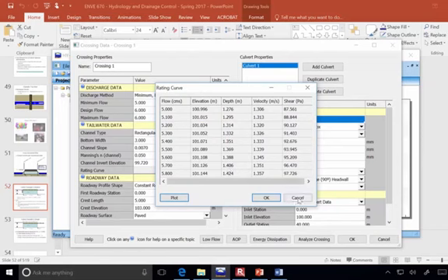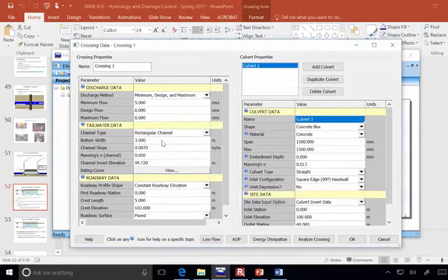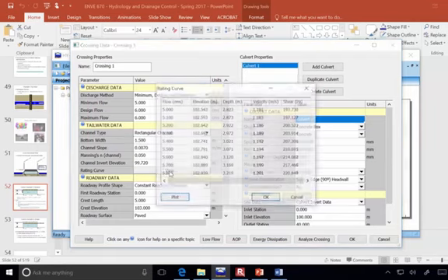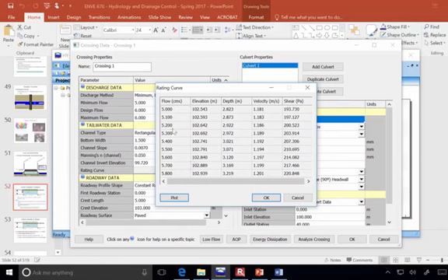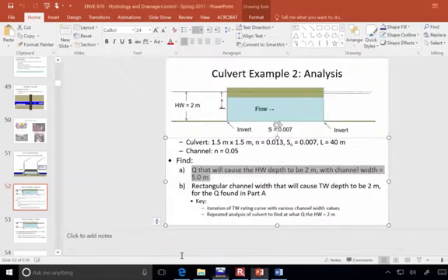So we can make it even narrower because it increased the depth of water from having the channel narrower. So we could make that channel instead of 3 meters wide, let's see what happens if it is 1.5. At 1.5 meters of width and 5.2 cubic meters per second, now it looks like it's too much. And so it's just kind of like an optimization process where we could play around with the parameters that are described and find out through iteration what is the correct channel width.